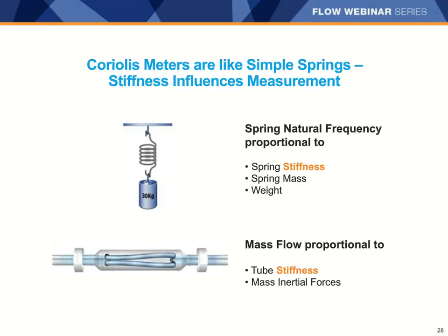Micro Motion has developed a way to use sophisticated modal analysis of the sine wave signals coming from the pickoff coils to determine from the tube vibrations what the stiffness of the tubes is without any influence from the fluid that is inside the meter. This is an extremely useful diagnostic tool because it allows us to confirm that the meter is sound and that the calibration is unchanged easily and without having to remove the meter or compare it to any reference standard other than the internal recording of the original factory stiffness baseline measurement. The original factory stiffness baseline is recorded at the time of the factory calibration, where the meter is first calibrated against traceable flow reference standards.